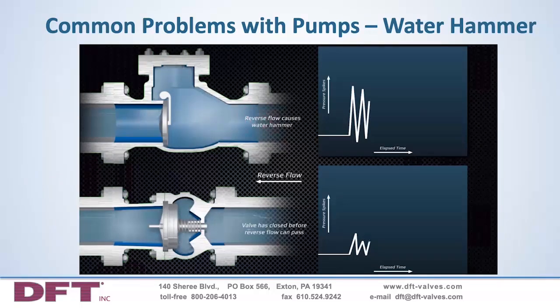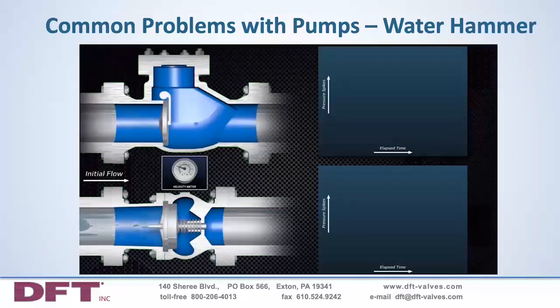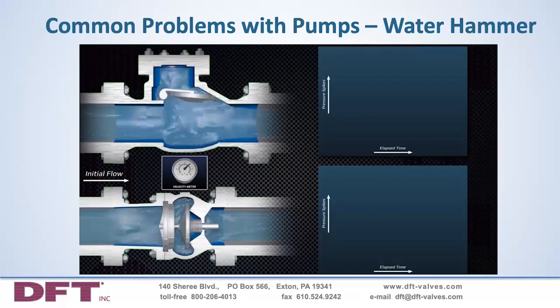The momentum of the fluid abruptly stopping creates a pressure wave that travels through the media within the piping system, subjecting everything in that closed system to significant increases in pressure and the forces associated with that pressure. Normally the pressure wave is dampened or dissipated in a very short amount of time, but the pressure spikes can do enormous damage in that short amount of time.